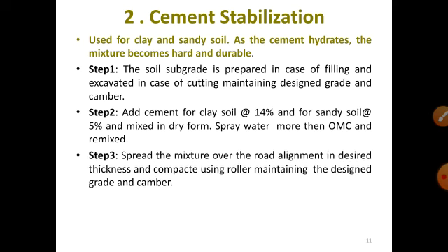Step 3. Spread the mixture over the road alignment in desired thickness and compact using rollers, maintaining the design grade and camber. Step 5. Sprinkle water up to 7 days for curing of cement.